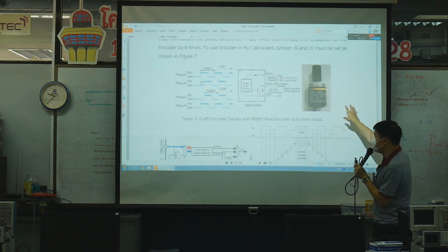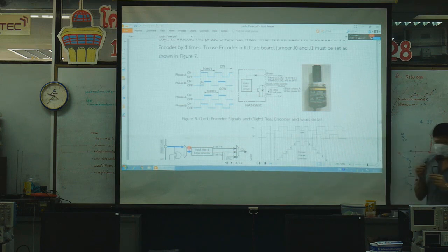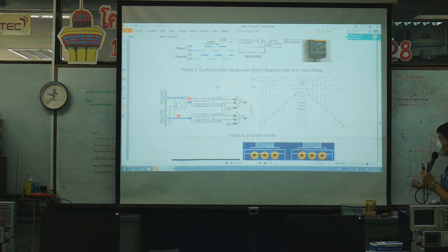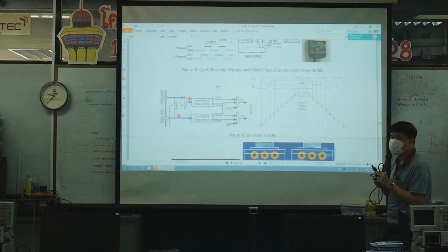So in this case, we will use this sensor or encoders in order to see the behavior of the rotations, and we can capture it. And in order to capture it, because this one is very popular in the factories, they have this module already inside our timers. It's called the encoder reader. Sometimes it's referred to as input capture.